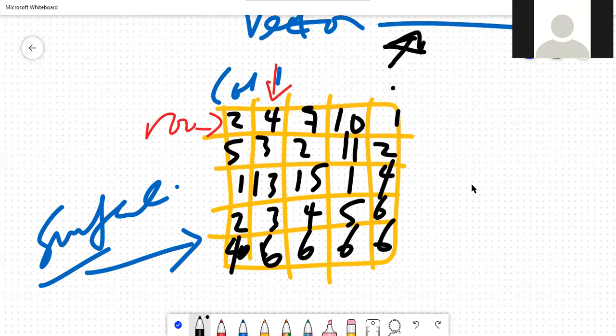Okay, so you can always mark areas that are visible. Let's look at something like 13. What's the viewshed of 13? 13 will see all these areas. You see here, see there, because the value there is higher. So the viewshed from 13 are these points.